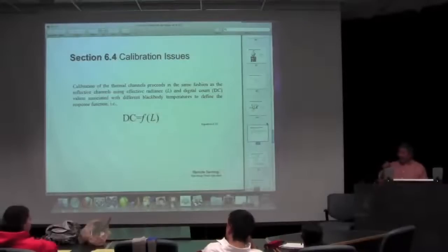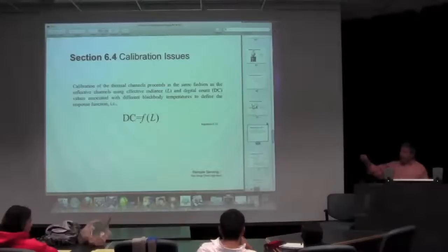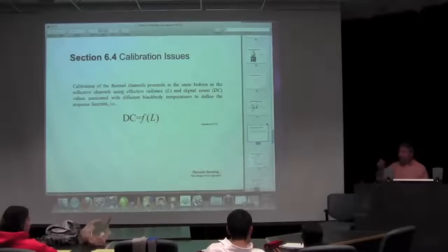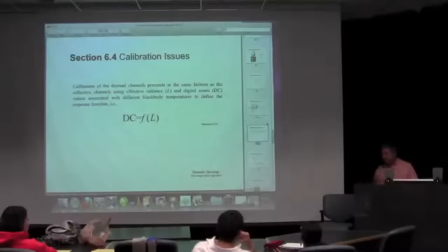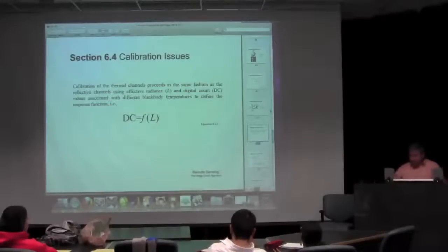So if your linear array that you're sampling the spectra with has 10 micron pixels, you want to figure out what that 10 micron pixel corresponds to in a bandpass, and then you want to illuminate with a slit through the monochromator that's smaller than that. If you over-illuminate, then yes, you're going to get all kinds of pixels lighting up. That's like a good test of your diffraction. Absolutely.